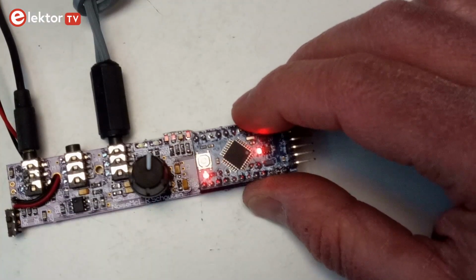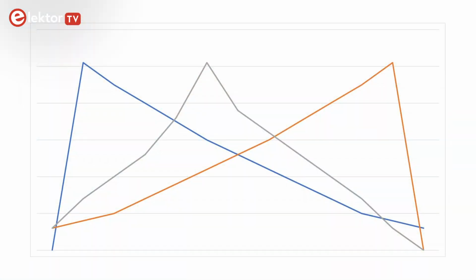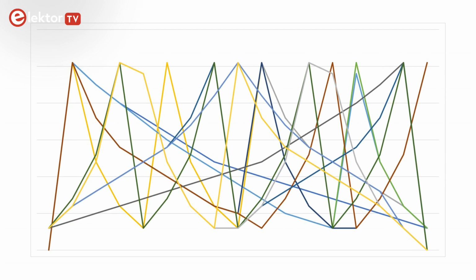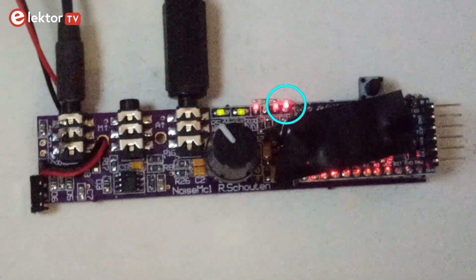The LFO itself can be modulated too, as it has 4 operating modes. First of all, it can be unmodulated, meaning that it's active all the time. Then there is active, but only when pressing the trigger button. The third option is to add accents from a pattern table. With the LFO mode potentiometer, you can choose between 48 rhythmic patterns, most with a length of 8 steps and 12 with a length of 6. The fourth option gives you 16 LFO depth sweep patterns, 3 of them with a length of 12 bars or measures, and the others have a length of 16. Again, you use the LFO mode knob to select the sweep pattern. LFO speed and depth are shown by a single LED.